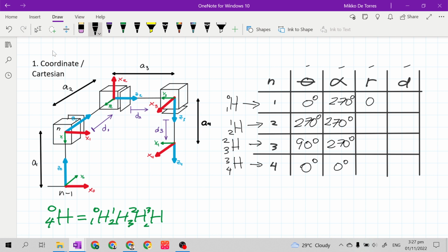So next is the homogeneous transformation matrix of frame 2 reference to frame 1. Now our x sub n is x sub 2. So the distance of frame 2 to frame 1 along x sub 2 is also 0 because along the axis of x sub 2 there are no link lengths. X sub 2 is pointing upward. There is no link length upward, along the axis of x sub 2.